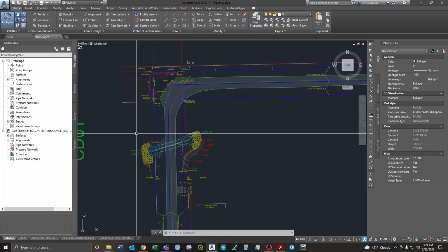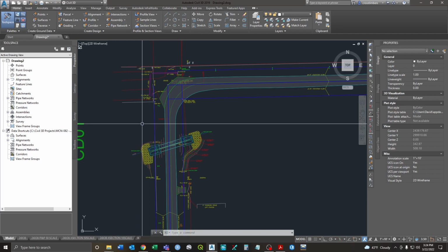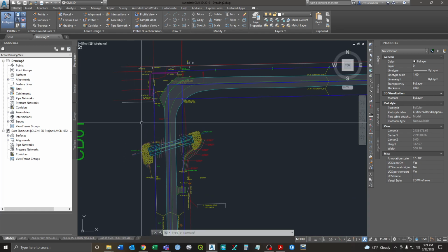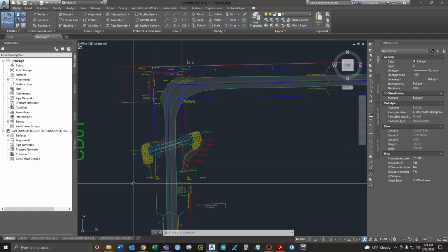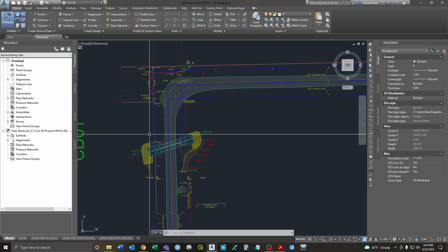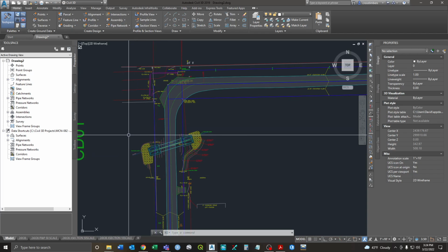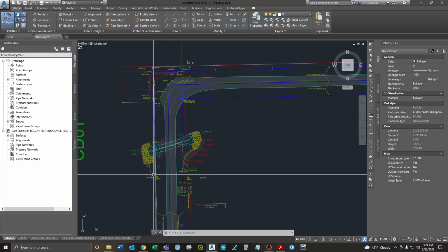So again, when you're doing the right of way, you want to keep it essentially on the same bearings as the section line and the initial right of way, because if you think about it, somebody's going to have to put a fence there or move a fence. Well, that fence is probably already on that bearing because it's so many feet off of here anyway. Sometimes you can make angles or different things, but think about fencing and what's the easiest thing. You don't want to go too crazy, and it's probably easier to just square it off, and that's generally the tightest space around there.